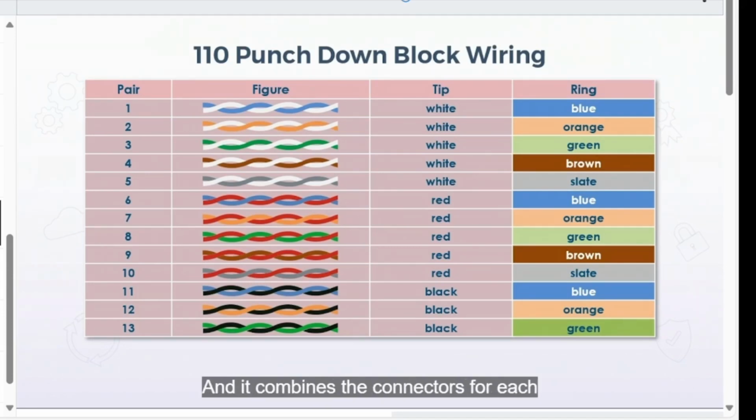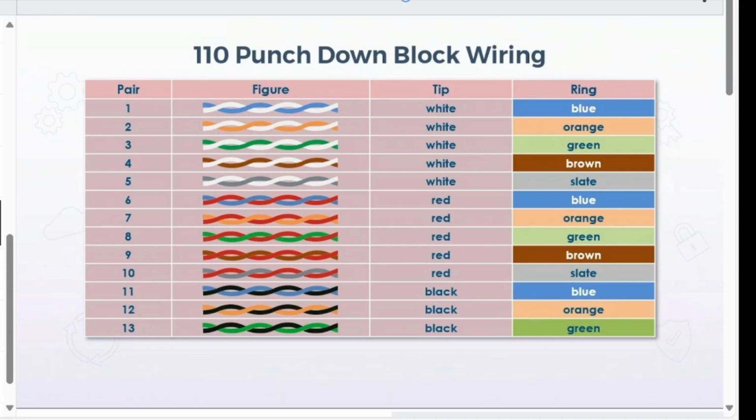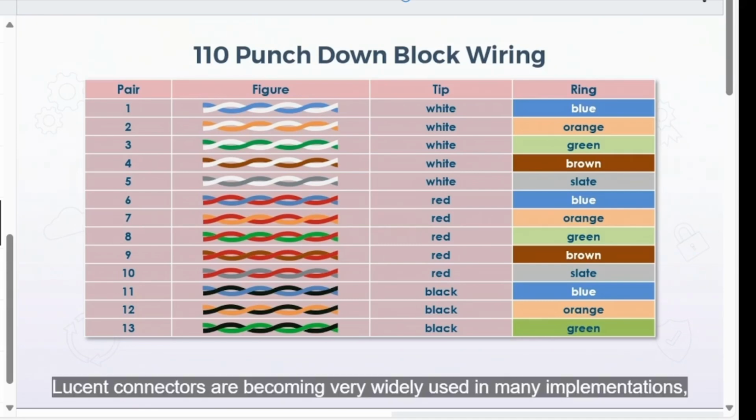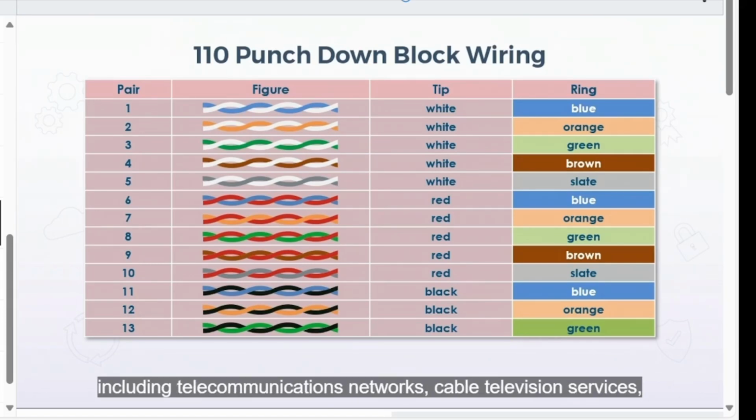But of the 25 connectors on each side, you might only connect the wires for the appropriate cable type that you're working with. So if, for example, you're working with, let's say, Category 6 twisted pair cabling for an Ethernet network, then only the first 8 connectors would be used on either side, which match the color configuration of twisted pair cabling.